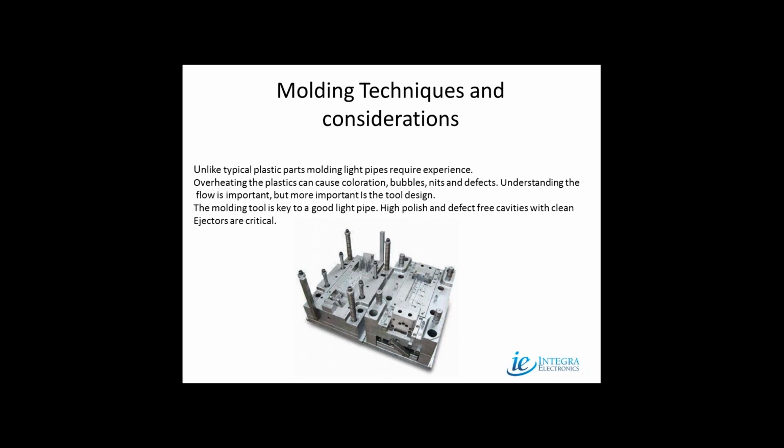Chris, is there anything you want to add on to the tooling aspects for light pipes? No, I mean, that's a great description, Mark. And the kinds of pitfalls you end up with is, molding a good design will take in mind things like sink, surface characteristics, the ability to actually inject the plastic into the mold, and these all have problems. If you don't have a good surface finish, like Mark mentioned, the light pipe won't be very efficient.